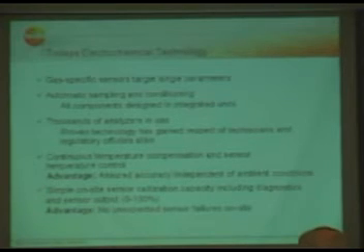This is a very nice feature, because if you put calibration gas on the sensor and it shows you there's only 70% or 50% left, at a specific limit like 30%, the analyzer tells you, please be aware, have a replacement ready. It can fail within the next measurement or within the next weeks or months, depending on how often you use the analyzer. That means if you calibrate the analyzer, you are on the safe side with the lifetime of the sensors, and you have a good overview of when the sensors will be used up.